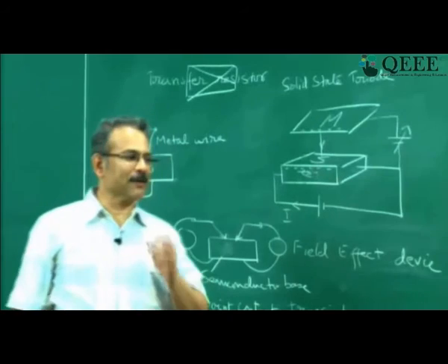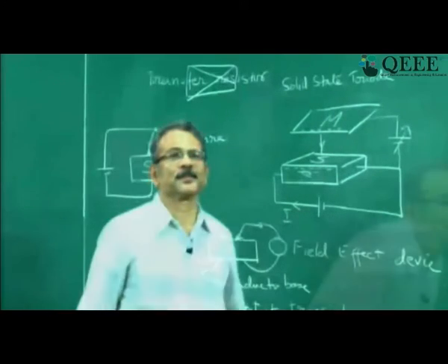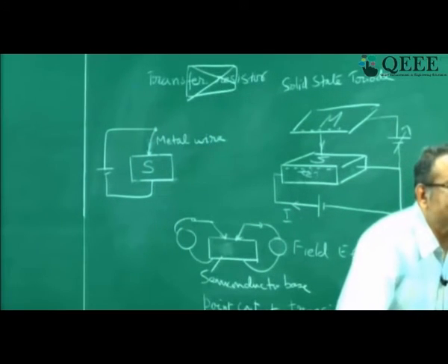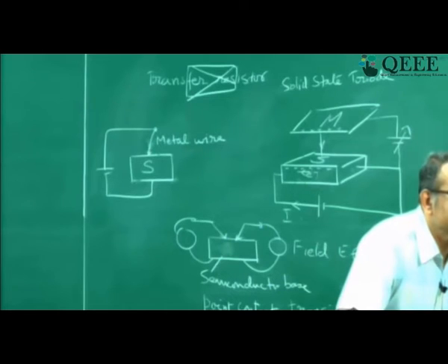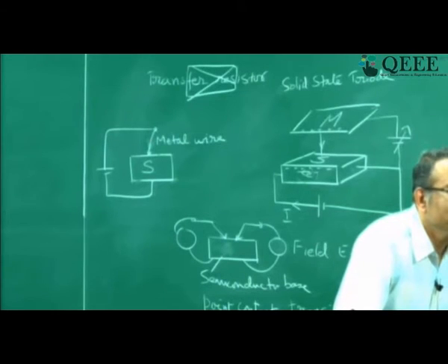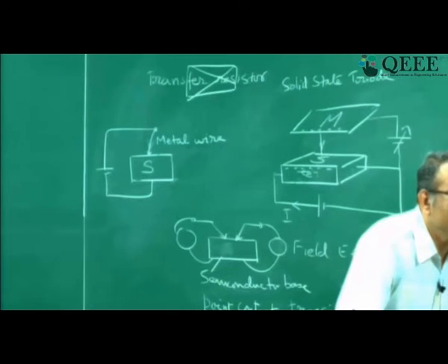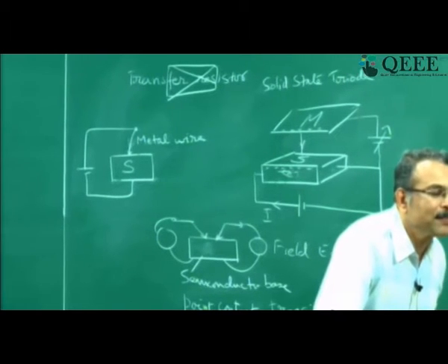Yes, so I am getting a question, let us see what the question is. In BJT input characteristics, if the collector emitter voltage increases, the potential barrier of the base collector also increases, or simply, collector emitter voltage is directly proportional to the potential barrier of the collector base junction. So how is it possible for the collector current to increase?